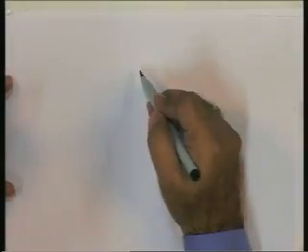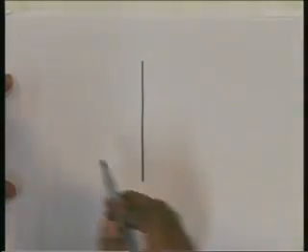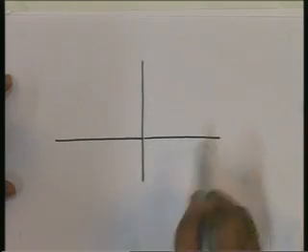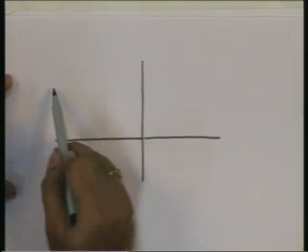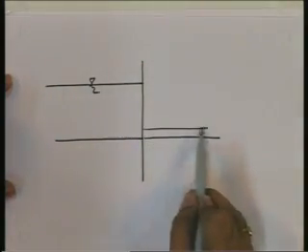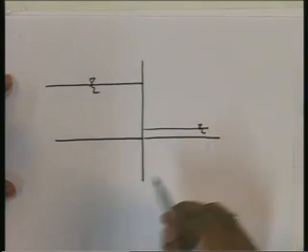So one of the remedial measures suggested is to keep some overburden or a surcharge on the downstream side, so that this uplift thrust can be minimized. It can be shown here in a conventional way. Suppose you have a sheet pile wall which has inadequate embedded depth, this is the upstream water level, and this is the downstream water level.